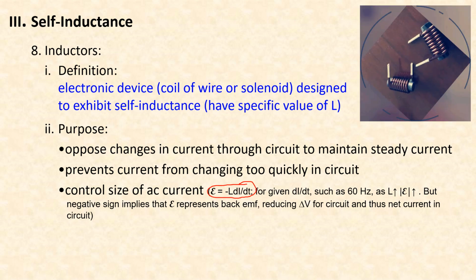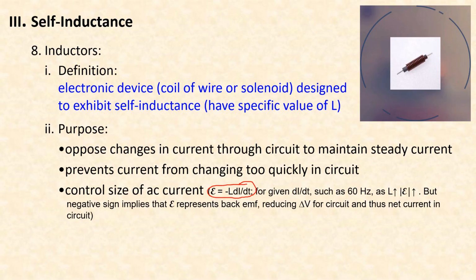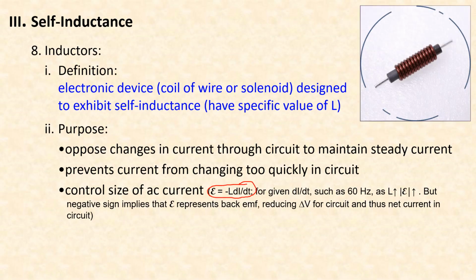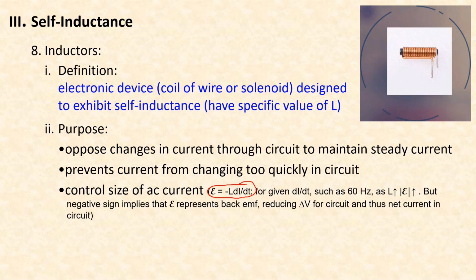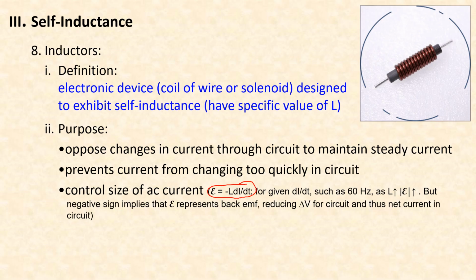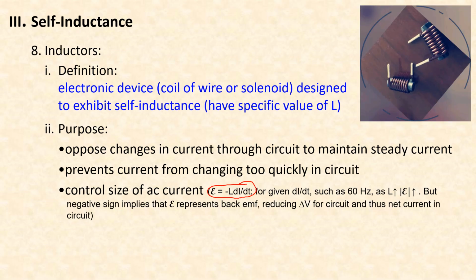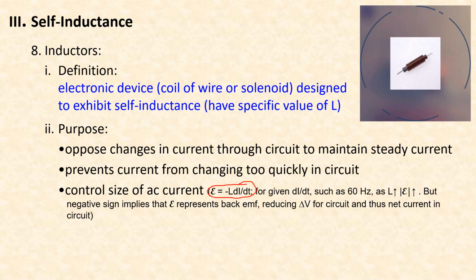This happens because the back EMF cannot be generated in the circuit if the armature doesn't turn. So when the armature turns and produces a steady back EMF and induced current that opposes a source current, the net current in the circuit diminishes.